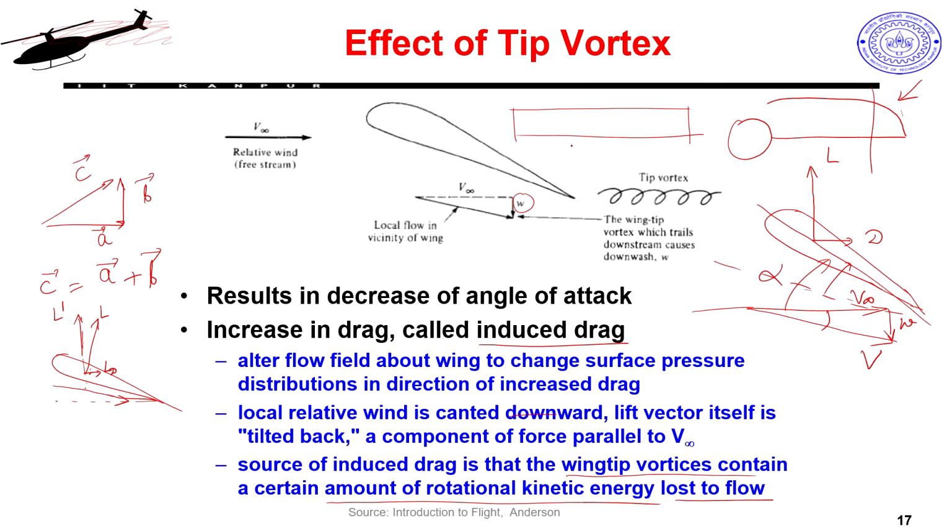So, imagine this wing versus this wing, right. They may have similar areas, but this guy will have better L by D because my induced drag will be less. I can just say that blindly, going with the same airfoil and same other things, while this guy having shorter wing will have poorer L by D because now a lot of area will be influenced by this tip vortex. So, that is the trick people use when they make gliders.